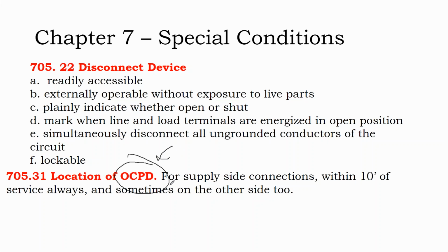That overcurrent could be a breaker. It could also be a fused disconnect switch. Sometimes you can save yourself a bunch of money if it's just one solar array being tapped into the grid, to not put a service panel there, but instead just use a disconnect switch you're already buying. Using a fused disconnect switch counts as your overcurrent protection.